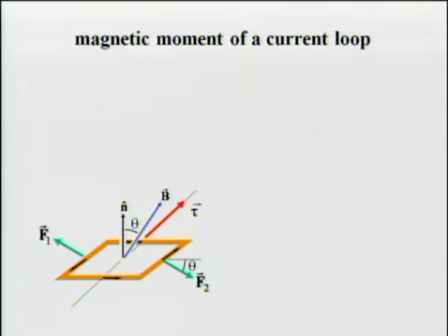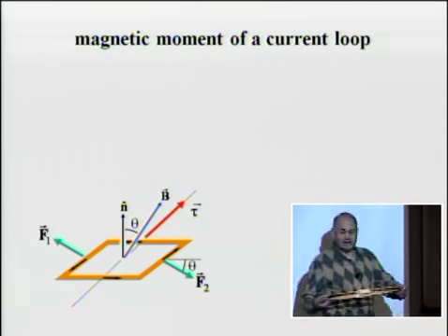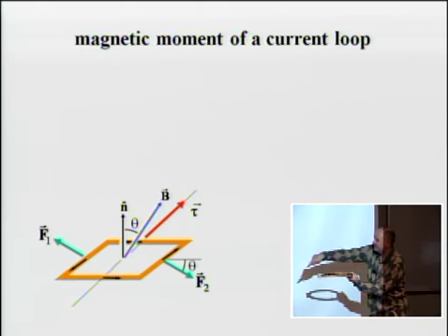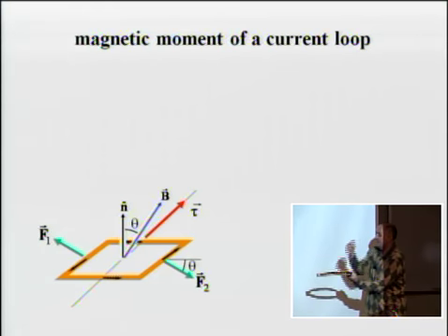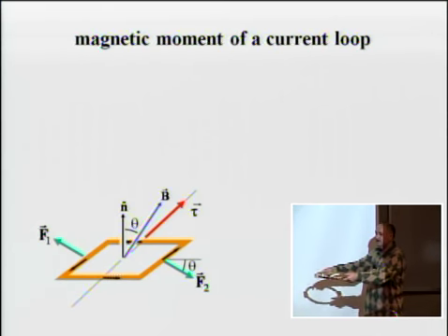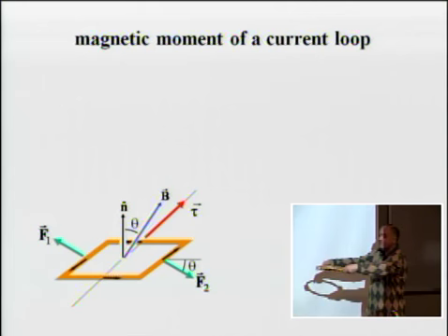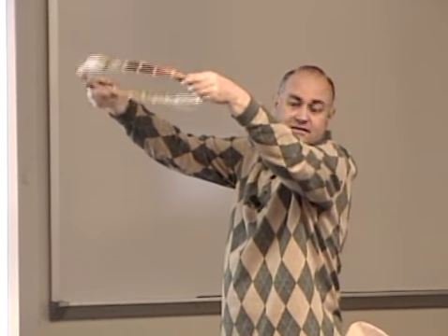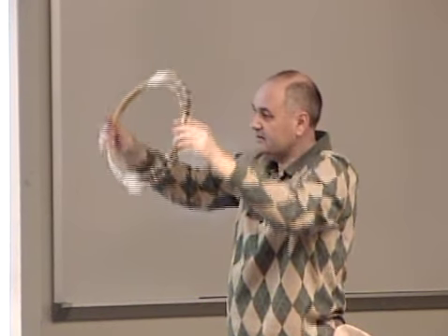So if I grab, let's say it's not a rectangular loop, but doesn't matter. In this configuration, if I thought about this loop, imagine that current in the loop flows this way. And magnetic field is this way. We figured out that torque is going to be in. Magnetic torque is going to be in, which means that magnetic field will try to rotate this loop which way? This. Right? It will try to rotate it this way.